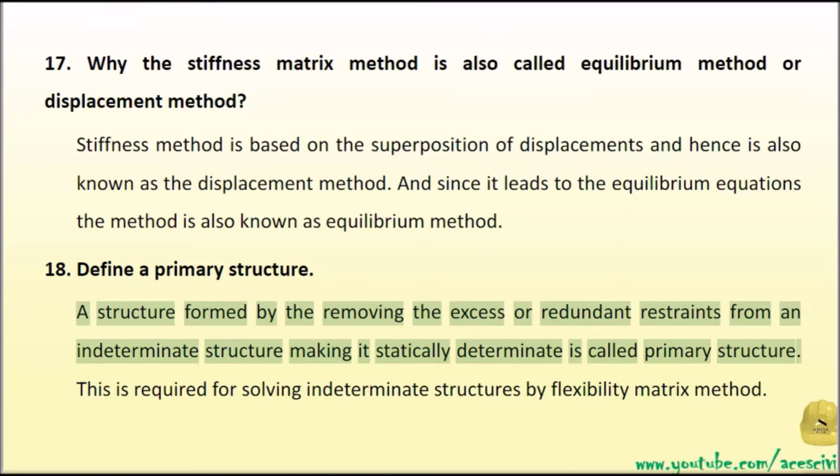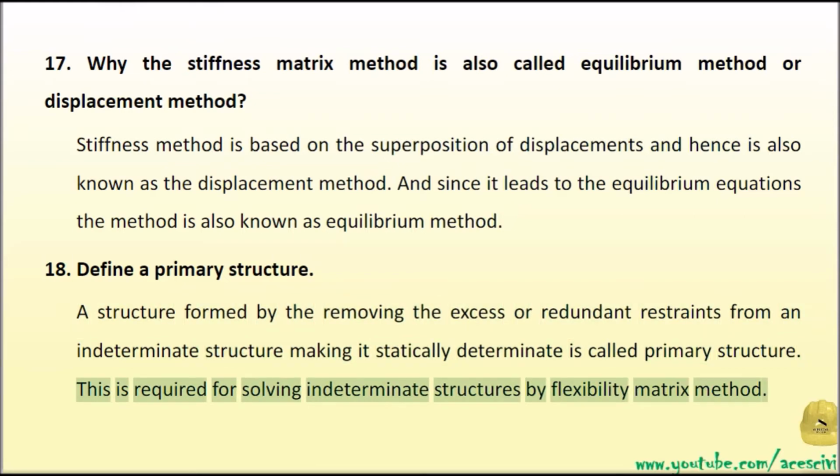A structure formed by removing the excess or redundant restraints from an indeterminate structure, making it statically determinate, is called primary structure. This is required for solving indeterminate structures by flexibility matrix method.